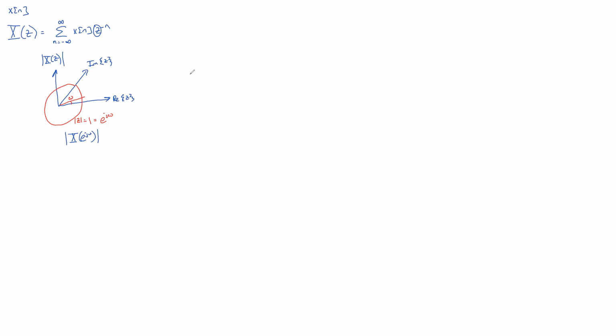Yeah, can you explain why when you have a finite set, and you take the Z transform of it, it blows up at Z equals 0? Oh, sure. So here's an example of an x of n, and we'll make it a simple finite length sequence. And you can read out your x of Z directly from it.